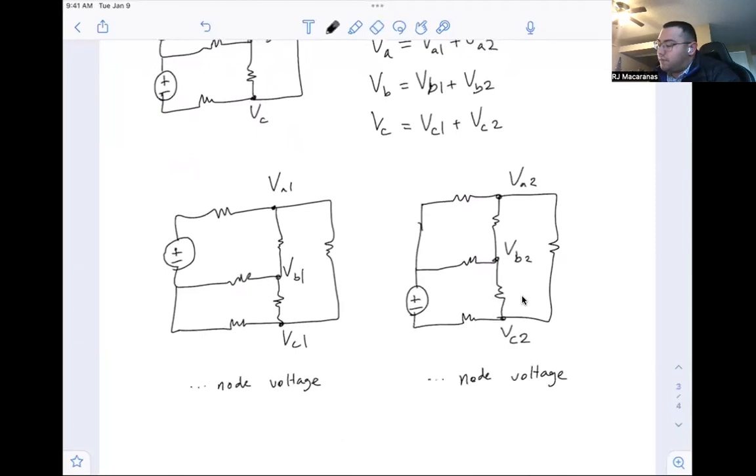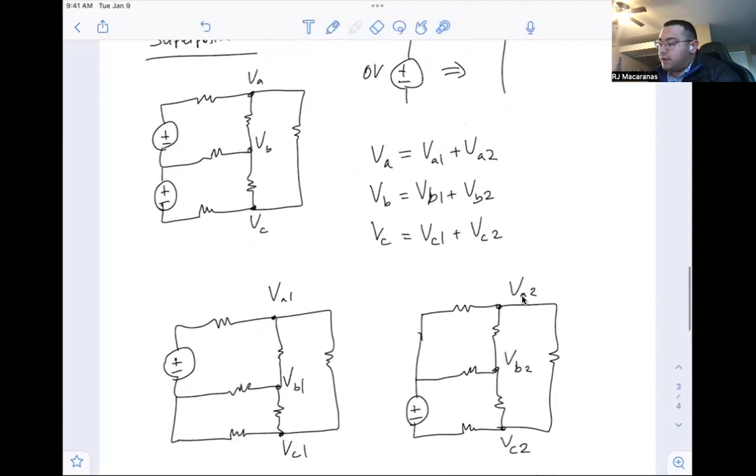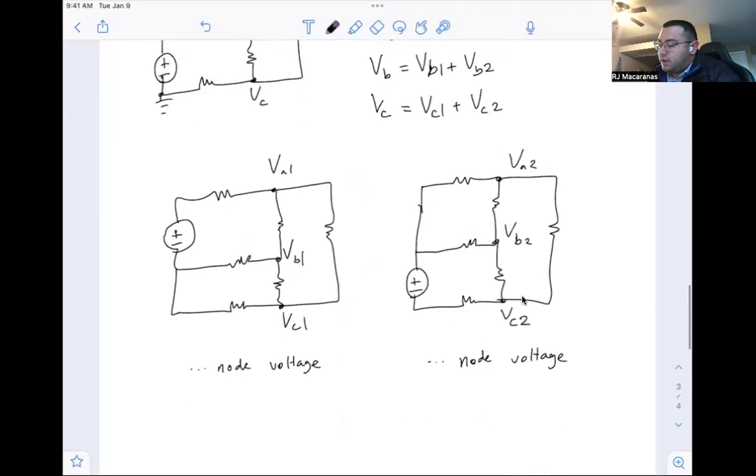Unless you wanted to, you could equivalently determine the equivalent resistance for both of these, right? So find the equivalent resistance, find the current going through, determine all the voltages everywhere, and you could go about it that way. And I forgot, these are the node voltages with respect to this ground. The ground will always be here.